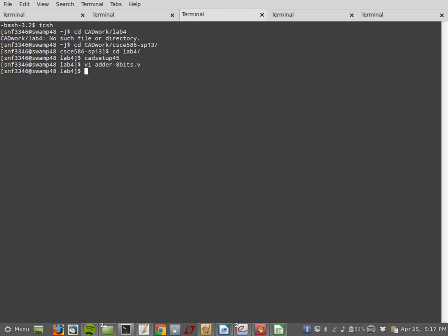Now, for synthesizing, we have a software that has a nice graphical interface, but you need to go into menus and specify parameters and all that. But we also have a quick script that, with one command, will synthesize your whole design and give you the results. So you don't need to open any software, you just run that script, which is much easier than going into that graphical interface. But there's only one thing you need to do, which is go into that script and modify it. That script is called compile DC, and you will find it in your directory once you start working.